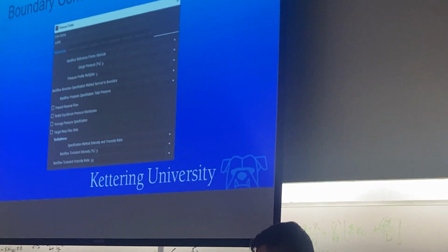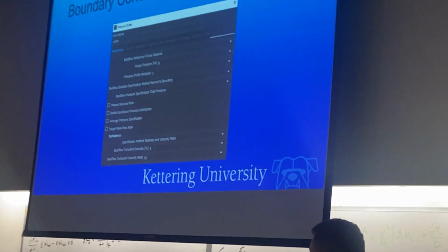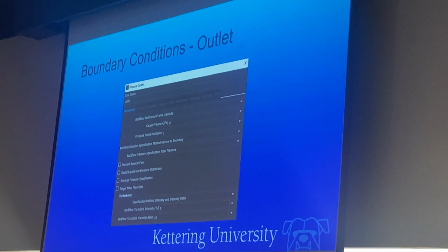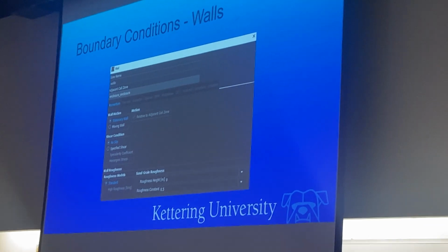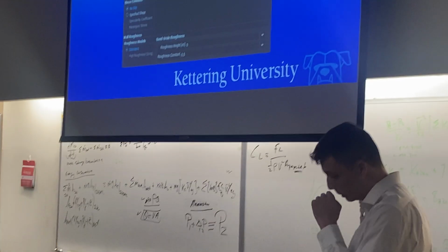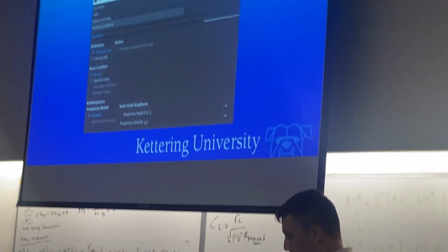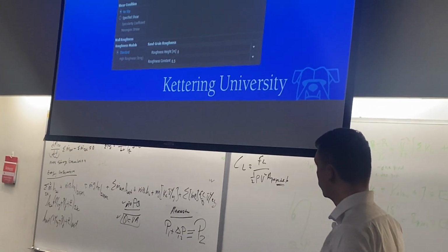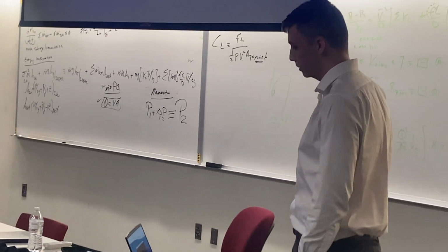And then for the outlet, the key parameter here is the zero gauge pressure. That is the most important part for the outlet. And also the same assumptions for the turbulent values. And then for the walls surrounding the domain, not the bottom wall, which we'll call the road, this is given as a stationary wall with the no-slip boundary condition and a roughness constant of 0.5, which was again a base value that the software recommended for this application.